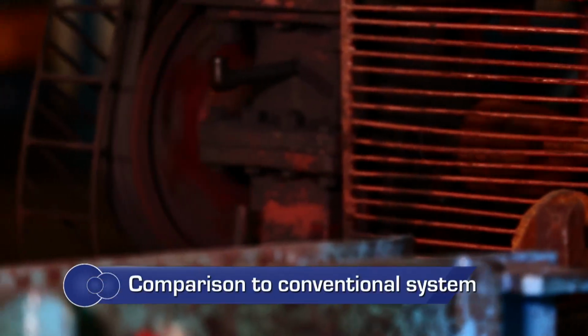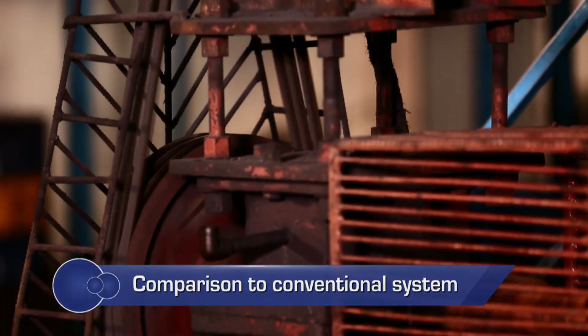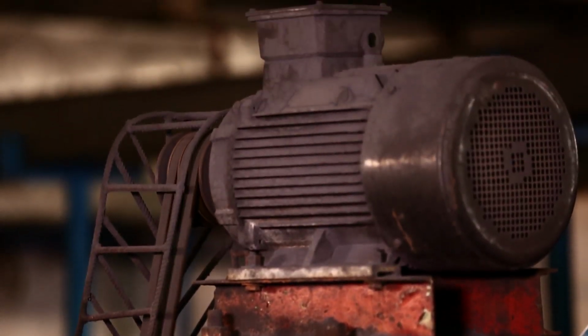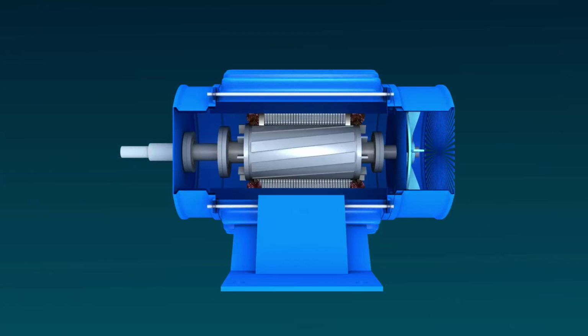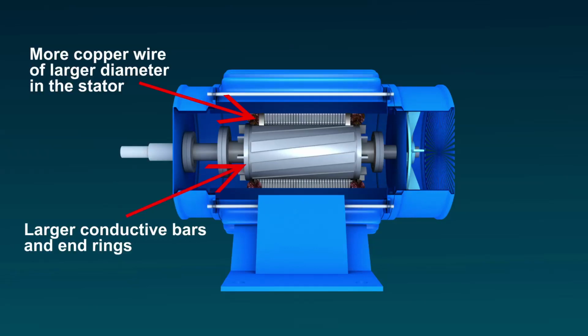Compared to conventional systems, the energy-efficient motors available in the market offer 80 to 95% efficiency depending on the size. Copper losses are reduced by using more copper conductors in the stator and by using large rotor conductor bars. Using a thinner gauge, low-loss core steel and materials with minimum flux density reduces iron losses.